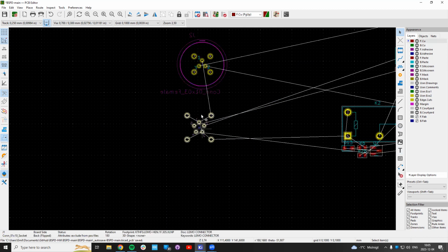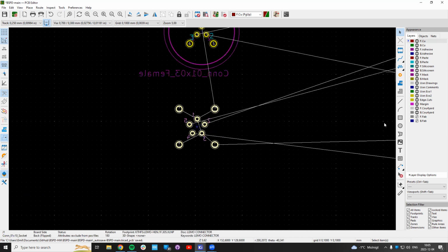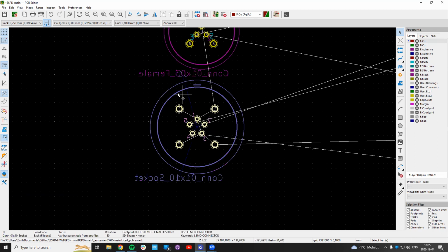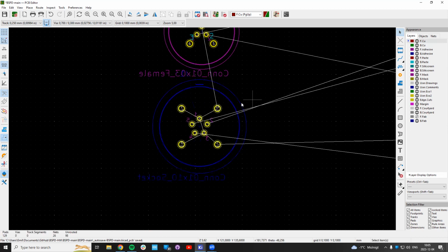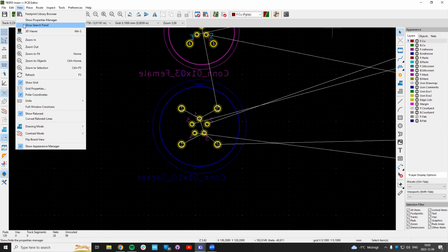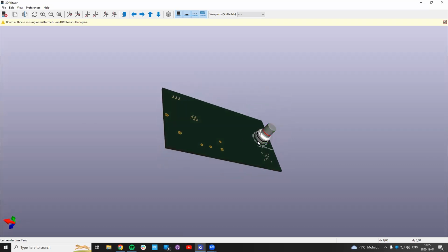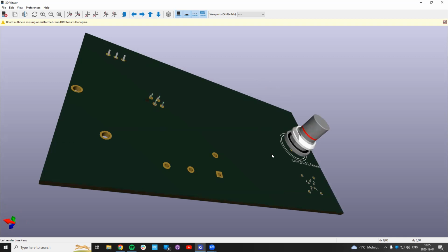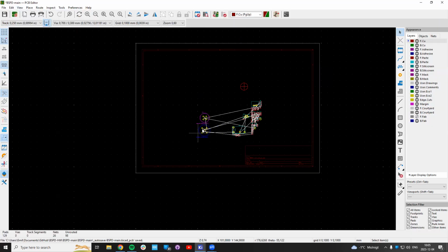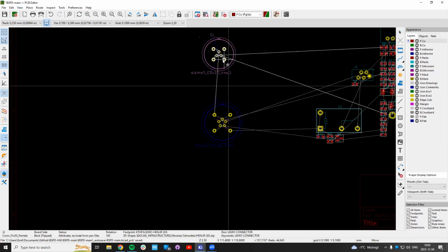The important thing here is this ring, you want to keep track of it, because how does a Lemo look? It has this metal part here. So if you take some through-hole component and place it inside the ring, it might touch the metal of the Lemo. It shouldn't, but it might. So you want to stay out of this ring with any through-hole components. Okay, but it's going to have 2 Lemos.